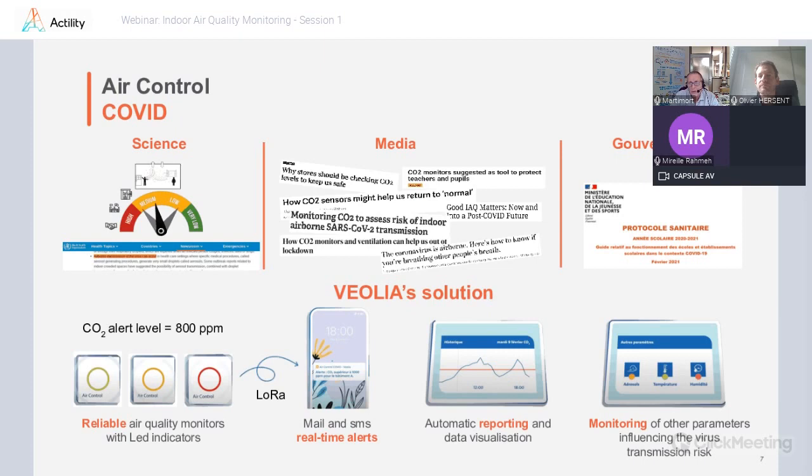Yeah, the outdoor pollutant is not CO2. In some urban areas with heavy traffic, the CO2 background can rise to maybe 500 ppm, which is anyway used as so-called fresh air to ventilate your building, so you have to consider it as a good thing because you have no way to do differently. But the probe that we make for outdoor is mainly related to particles. Just in France, PM2.5 is killing more than about 70,000 people per year, more than COVID, by the way. So this is a real concern. Particles are the main killer. After that, you have NOx and ozone, but CO2 is not really a concern.